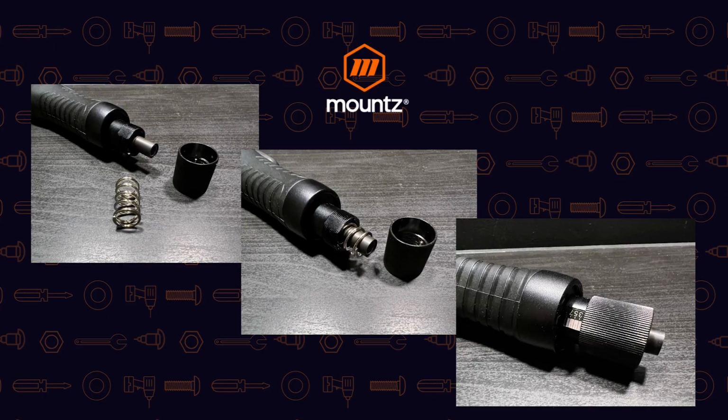So a torque screwdriver, an electric torque screwdriver, in this case a clutch tool, is going to have a certain range that it can meet based off of the spring that is in the clutch mechanism. Now, these tools do have reference marks on the nose cone. As we dial that nose cone up towards the body, we're going to be increasing the torque.